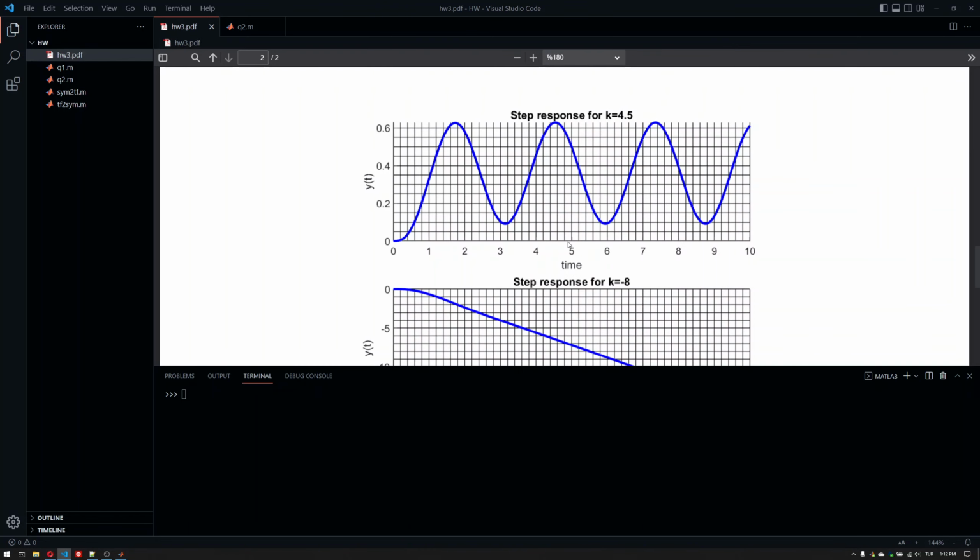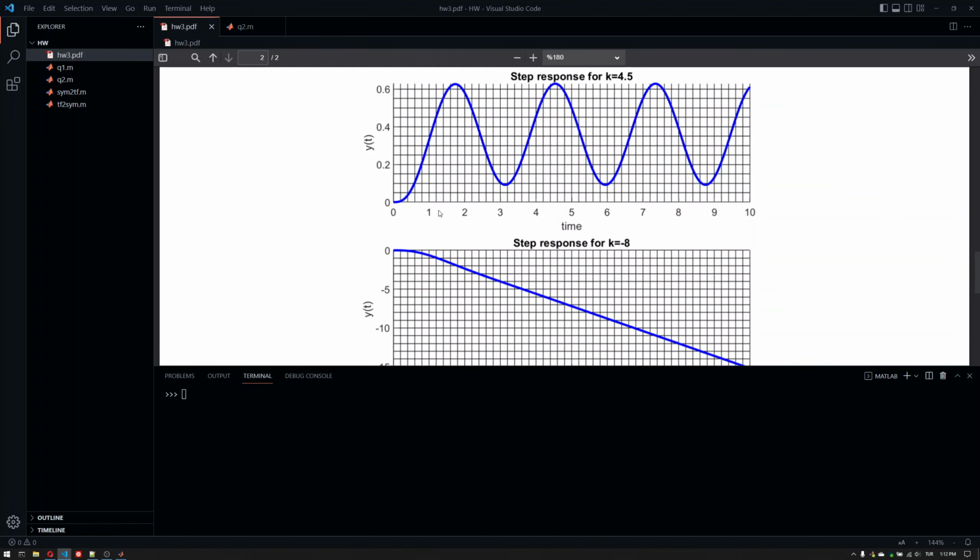And there's another conclusion that I can draw from this. If you think about a certain third order system, when we calculate the stability margins of a third order system, what we most of the time end up in is a j omega crossing with a certain omega value and an origin crossing.